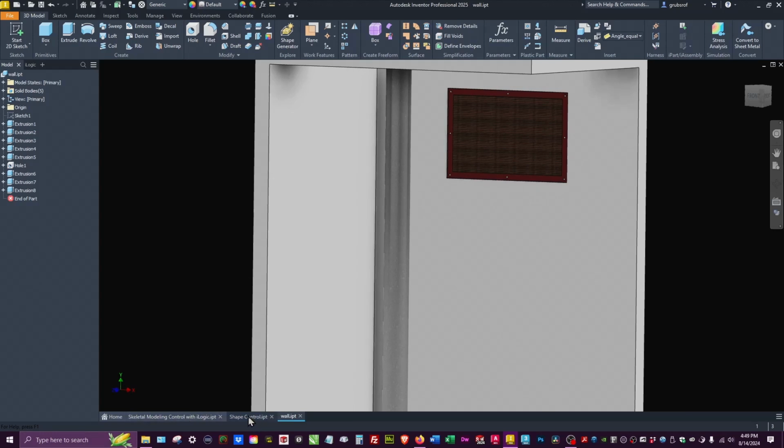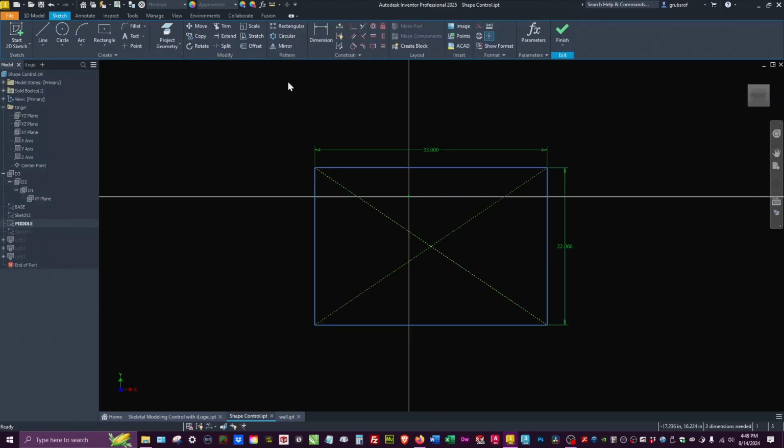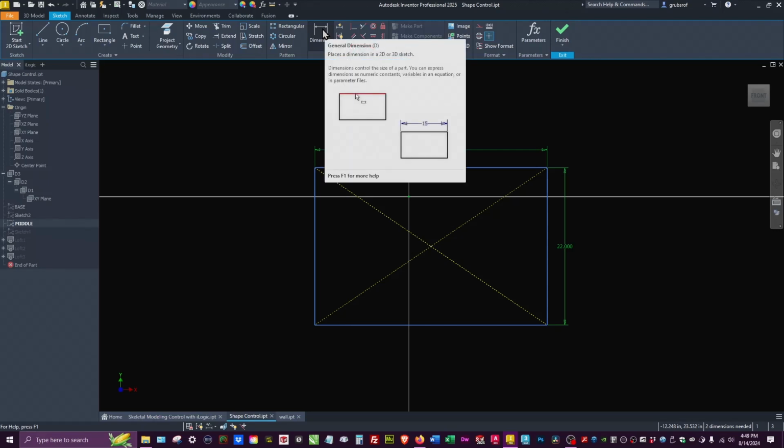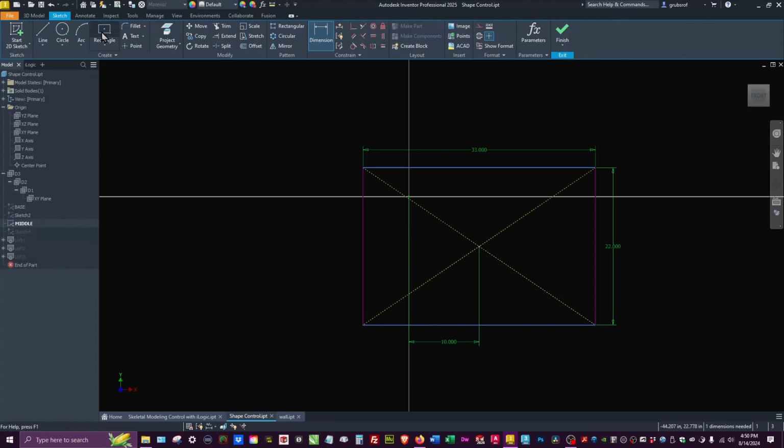So let's go back into the shape itself. And now I am going to control that middle. So let's go back into this middle sketch. I already know how I'm getting around that, but you'll just see the reasoning why. So let's go ahead and pick this. We're going to call this LOC for location. And this is going to be horizontal, and we are going to do that at 10 inches, equals 10. I'm going to hit enter on that so you can just see it update.